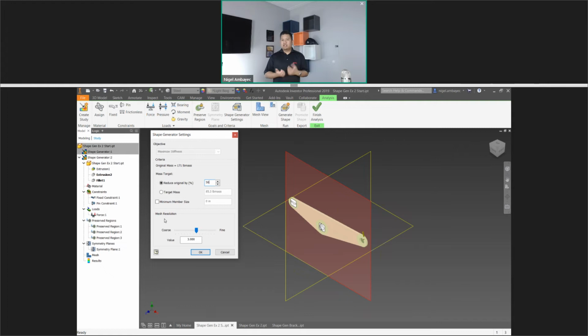And so generally what I like to do is stick around the middle, around a value of 3 for the mesh, and run a simulation. If I'm getting something that is expected, right, if I'm taking material out in ways that make sense based on where I'm loading it, then I start going into finer and finer mesh until I get it refined enough where I get my finished shape.